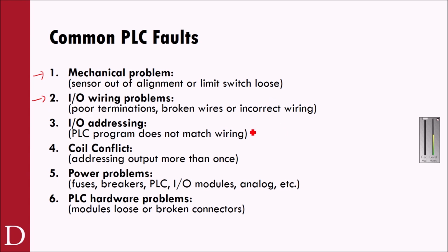I/O wiring problems, it is possible that there's some poor terminations, especially if you're looking at a brand new install and something's not working in your troubleshooting. I've seen everything from, you've got a screw terminal here and somebody wires into that screw terminal. I'll kind of give you some hidden lines underneath here, and actually the screw is pressing on the insulation of the wire. I always like, when I go into a screw terminal, to see that insulation is actually clear, and I can see the strands of the wire going in there. So just so that doesn't happen. This has bit me in the butt before.